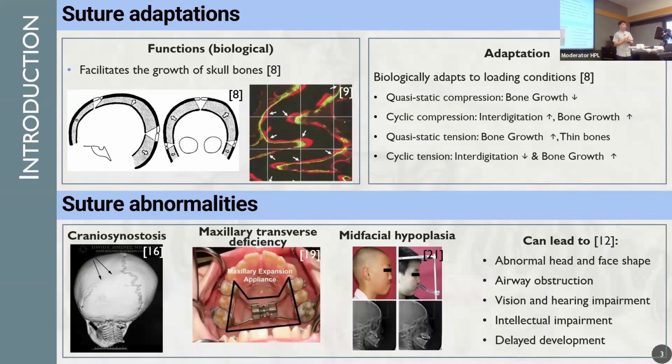Is there any reason that you look at the maximum principal strain? We can look at various different things, but maximum principal strain is mostly associated with tension, while minimum principal strain is associated with compression, though in some cases it can be above compression level. I just wanted to see whether it is in tension or in compression, because previous studies say that with tension it behaves one way, but with compression it behaves differently.